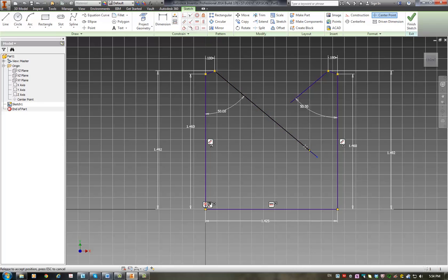And then I can just drag this. If I left click here and hold it, I can move this to another side, or I don't have to do that. I mean, I can just trim later. And I need one more line. I will click somewhere and just make sure it doesn't capture all these. You see, now I have these small black dots. Now this is connected, giving me a constraint to the end point, to the midpoint. Just make it completely outside so it doesn't catch anything. Or, for example, somewhere here that I don't have anything.